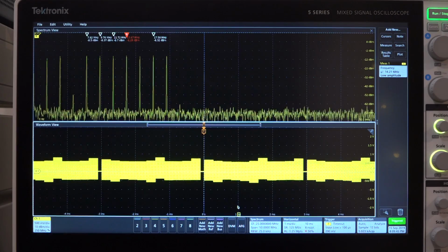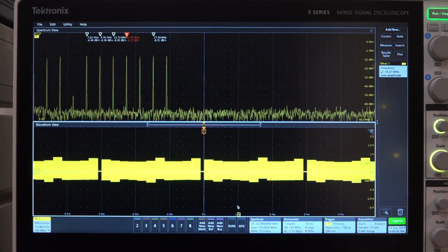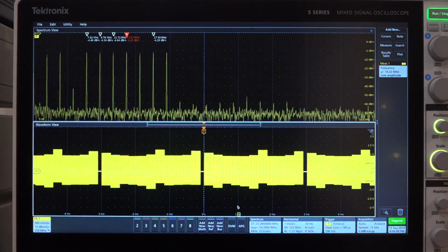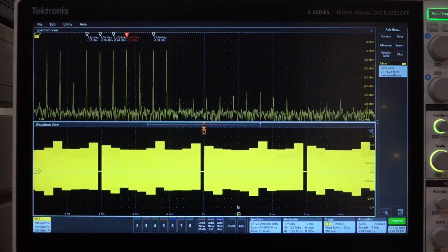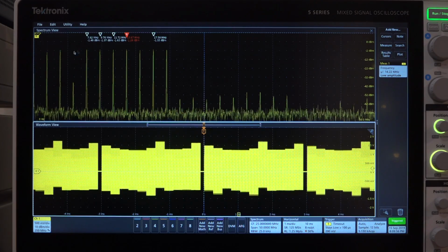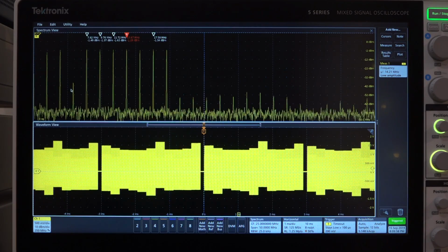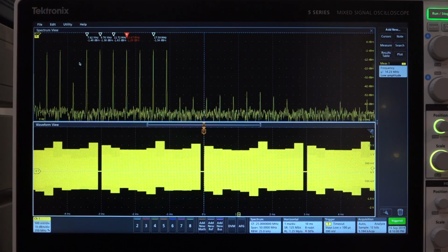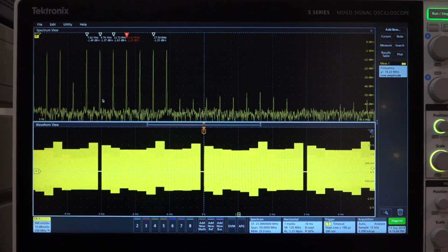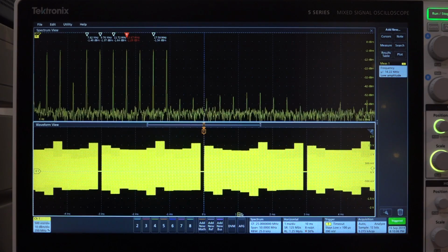Let's say this one. Okay, I'm going to increase the power here slowly. You can see the amplitude is going to grow. There you go. It's going to be a bigger jump and another big jump. And take a look. You can see that we are quite a bit worse than we were before. Compare this to what we were getting from the unit earlier. Now we have about 35 dBc from one of the tones in the missing tone test. That's quite a bit of a degradation.